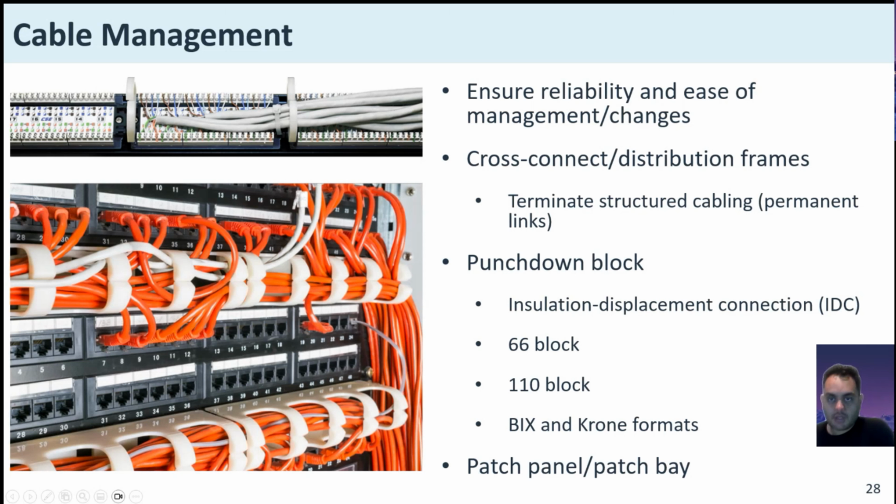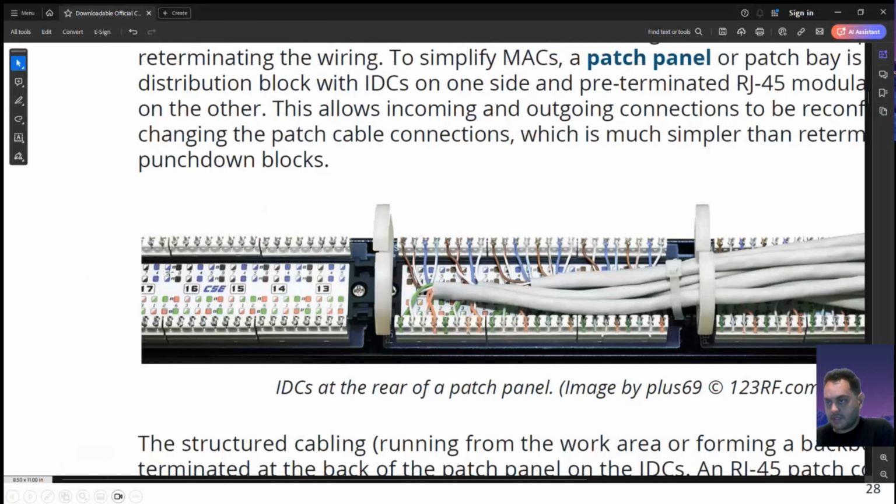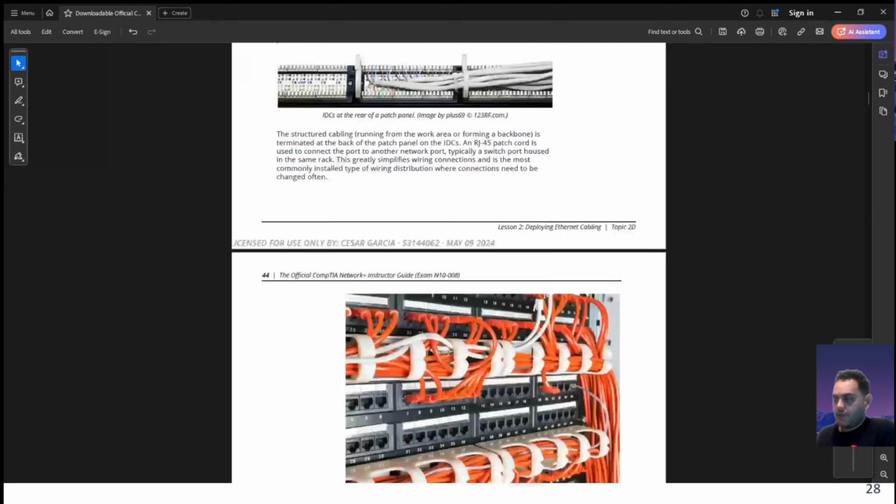And these here, if you take a look, let me see if I can zoom in here. Can you guys see this, the A and B? This A and B is going to tell you exactly how to map out your port. So for instance, 17, if you wanted to go with A, you'd follow the diagram up here. If you want to go with B, you follow the diagram at the bottom. And you would just map it out. So here, you can see we have A. You got brown, stripy brown, blue, solid blue, stripy blue, and we're still dealing with A. See? Then we've got stripy green, or green, stripy green, orange, so on and so forth. And everything that you work with will have a diagram on it. Even these ports that go into the wall.